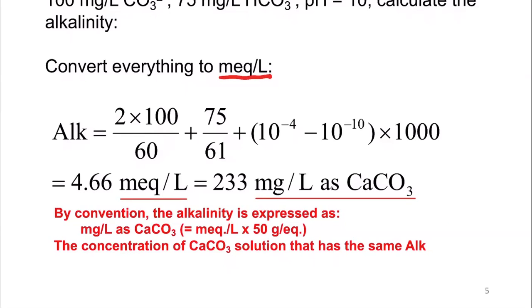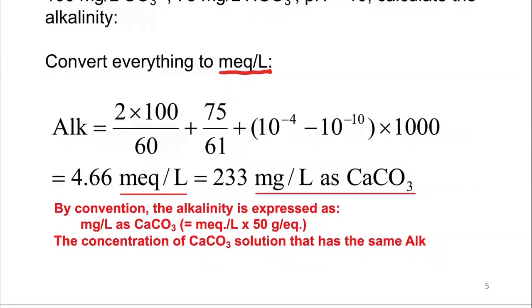But actually, not all of the water treatment or wastewater treatment facility staff are engineers. So they want a term that is more straightforward, because the concentration of calcium carbonate is just the concentration of rocks or limestone, right? So whenever they want to tune the pH or understand the alkalinity of their water, they want to understand it in the amount of limestone, okay?